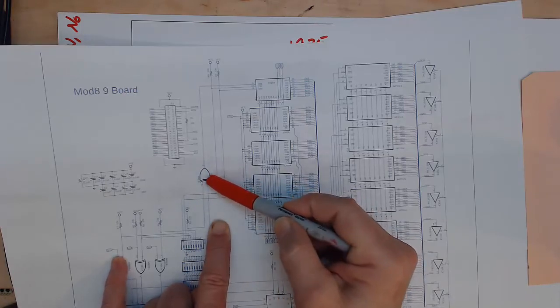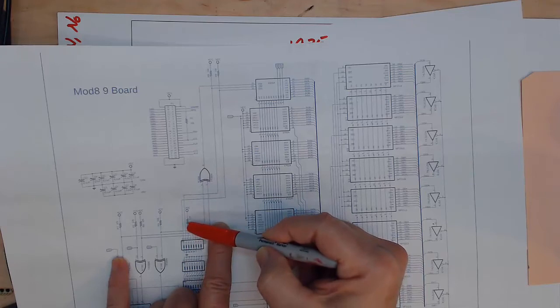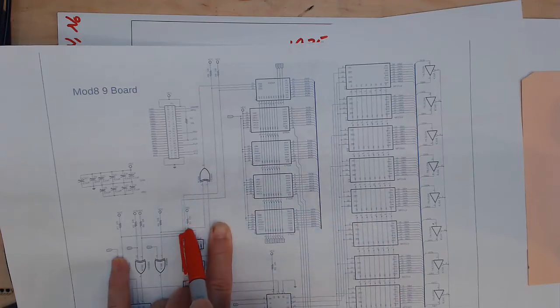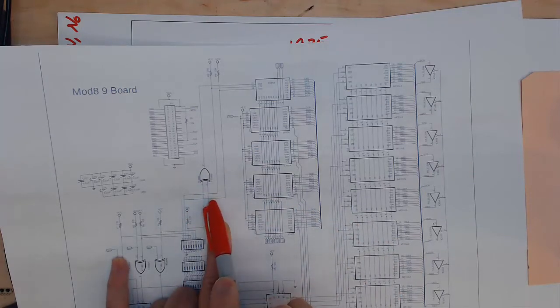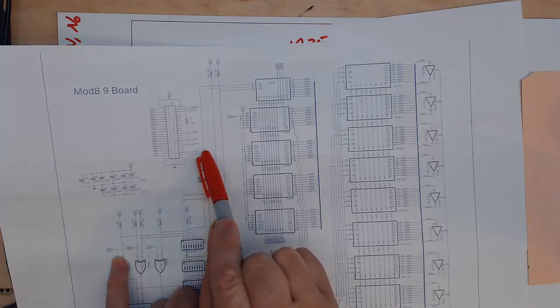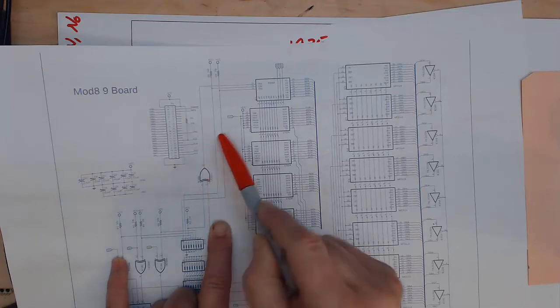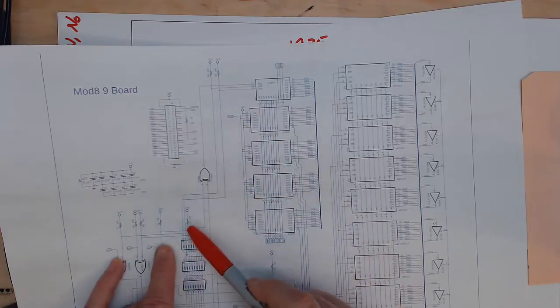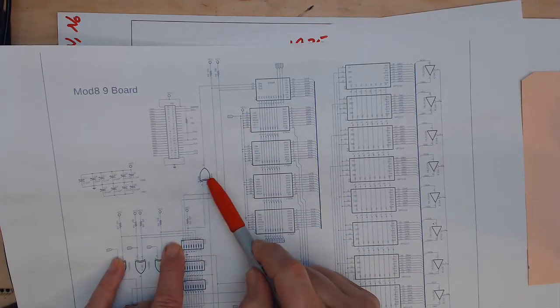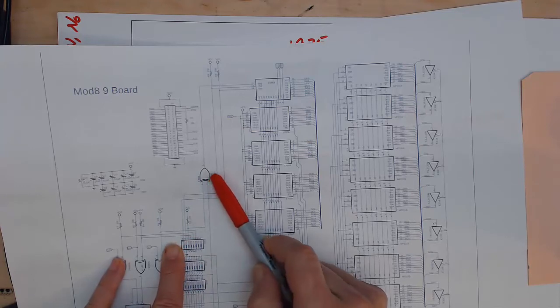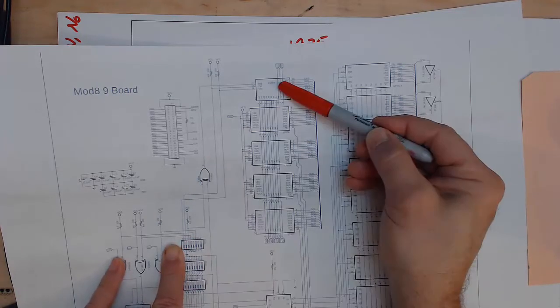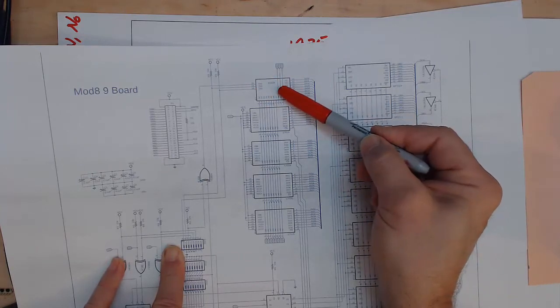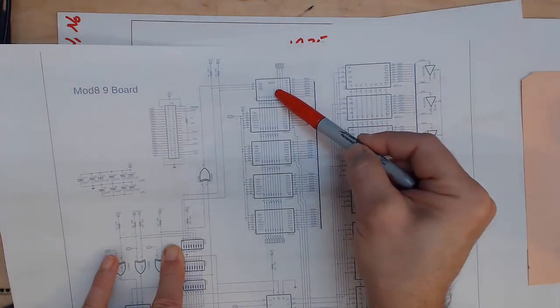So if that's the case, we would take this switch and open it up, so this resistor would pull it high, so whatever comes in when this is enabled, it would invert that, so now this is enabled active high. So that's what this logic was for. That's why we had 3 switches here, and this exclusive OR was being used to invert, so that no matter what number was written on the top for the chip select pattern, we could match that with this board.